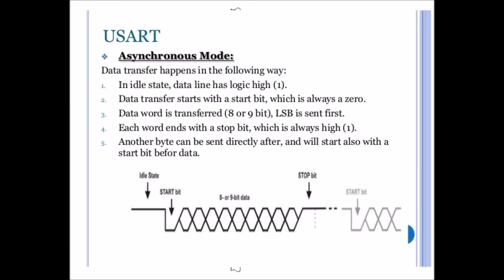In those times, the fastest asynchronous voice band modem could achieve at most speeds of 300 bits per second using frequency shift keying (FSK) modulation, while synchronous modems could run at speeds up to 9600 bits per second using phase shift keying (PSK). Synchronous transmission used only slightly over 80% of the bandwidth of the now more familiar asynchronous transmission, since start and stop bits were unnecessary.